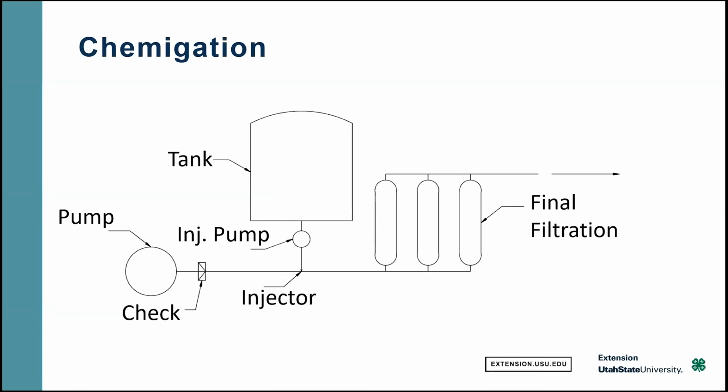And so you may be able to use a different type of protection device. But most of the time in drip irrigation, we're going to be injecting something. And so having some kind of protection device is important. If we're injecting something, we're going to have a chemical injection tank. We'll have an injector pump. Having a pump that is properly calibrated is important.